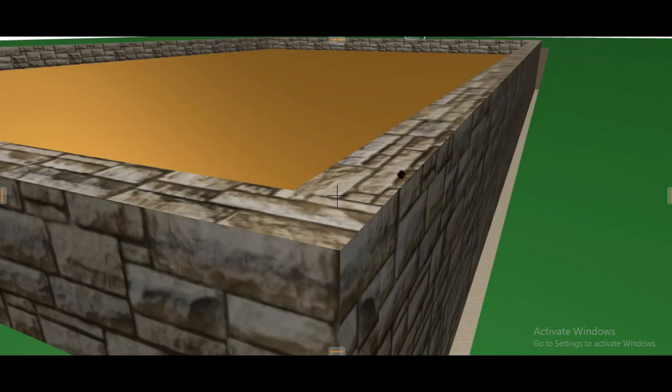So when I'm now writing this into the squaring column, I start with the length, that is the mean girth all around, and I follow with the depth, that is 1.10. So this 200 now across from this edge of the wall to this edge, it is less than 300. I simply write it in the description column. So if I want to get the volume, I multiply the length by the depth and finally by 0.2 meters to get the volume of this foundation wall. So it is that volume that I carry out to the Bills of Quantities.